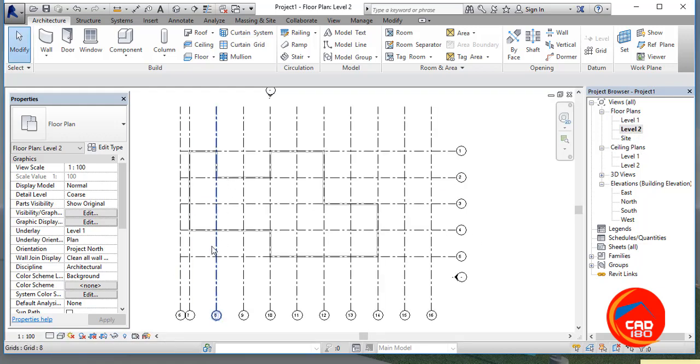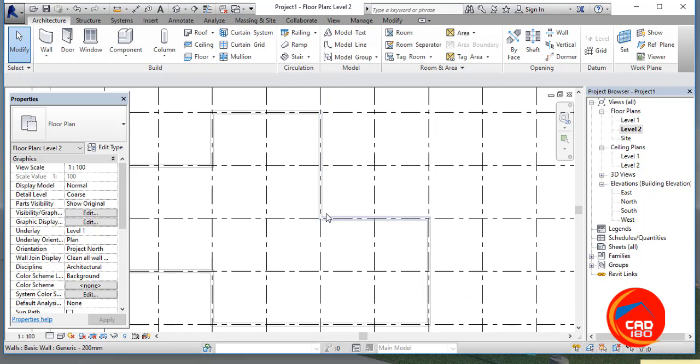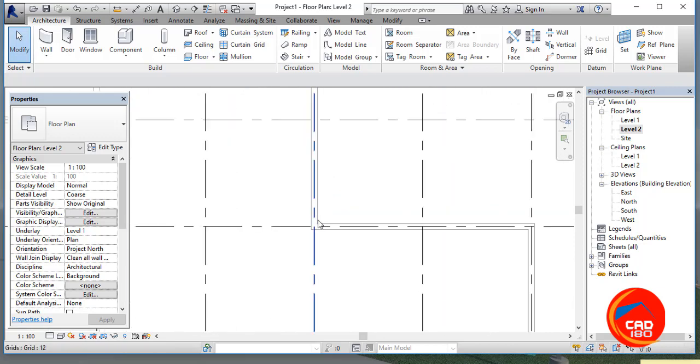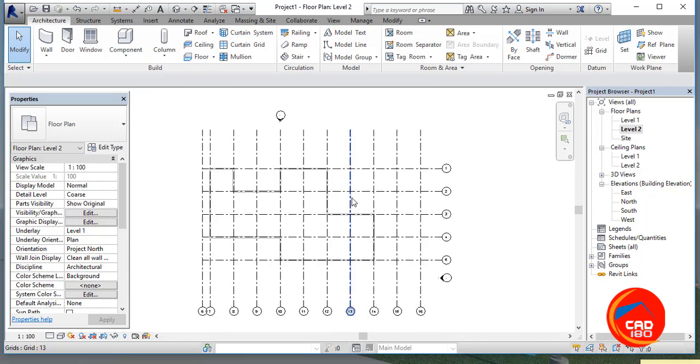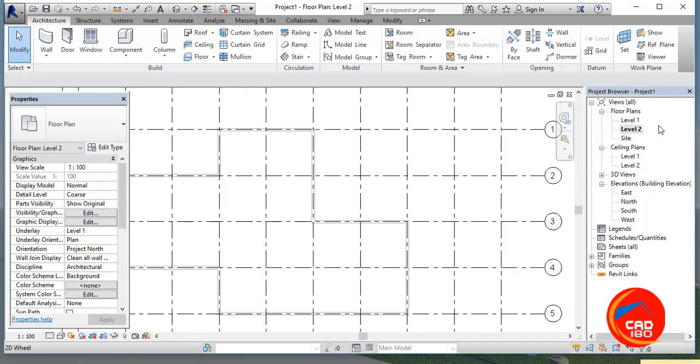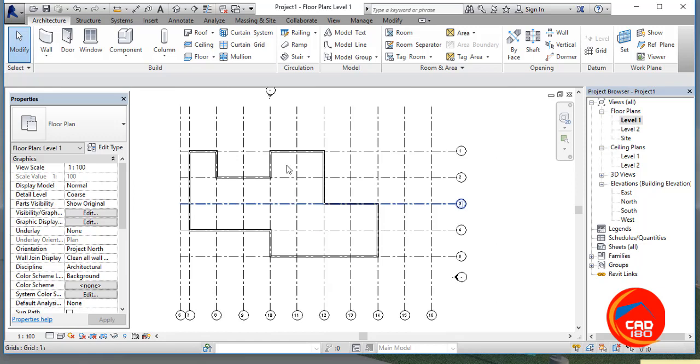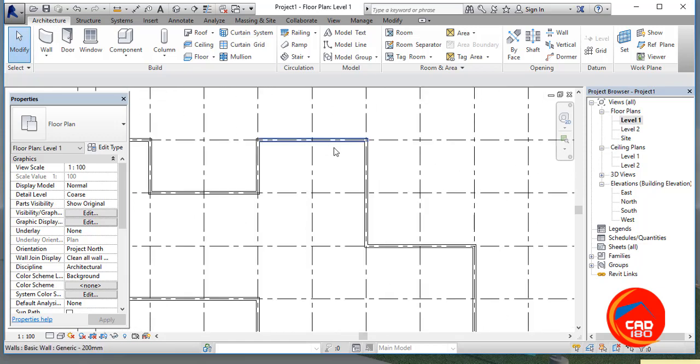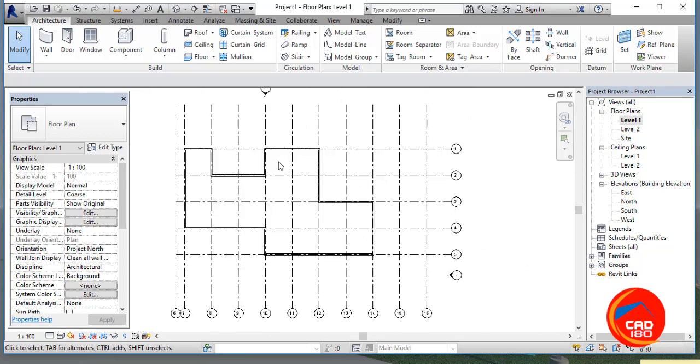Take the same, but you can see there's a fading, it shades. Okay, so that's how you know it's another level. And if you are in your current level, you can click here and see that the border line is more attractive and brighter than that. Okay, so now in this way we will create the wall.